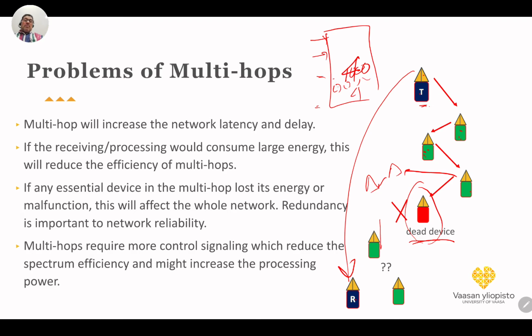The meters can connect to each other by using multi-hop. Then finally we have one data concentrator that collects the whole data, and then we use, for example, a cellular network to transmit the information. So multi-hop communication can be useful for many different applications.